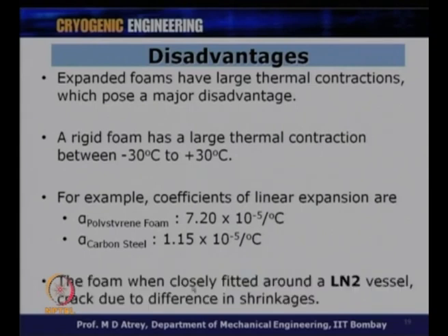So the foam, when closely fitted around a liquid nitrogen vessel, will crack due to the difference in shrinkage. The foam material may crack if it is subjected to thermal cycling, coming from LN2 to room temperature and again going down to LN2 temperature. So the reliability could be questionable in this case.